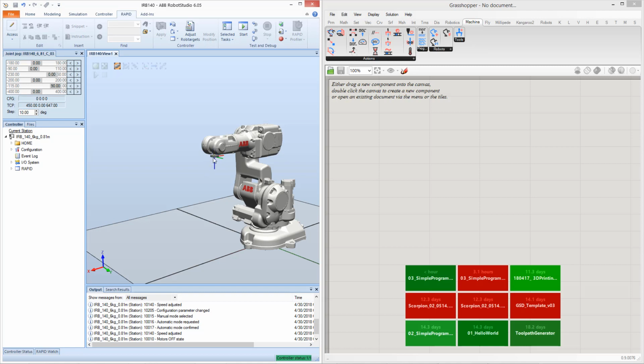So as you can see, the coordinate system of the TCP right now is similar to the global one, except for a 180-degree rotation around the y-axis. So you can see that the y-axis is the same, but both the z-axis and the x-axis are inverted. The z-axis is pointing down and the x-axis is pointing inwards.